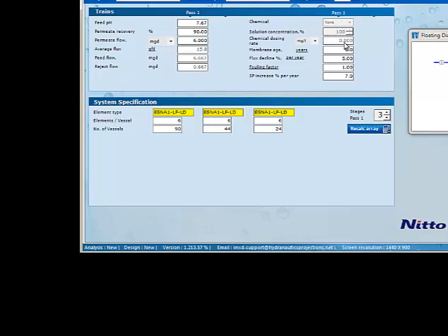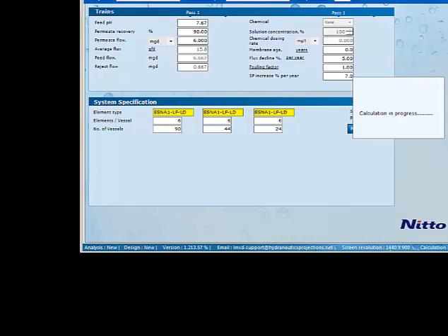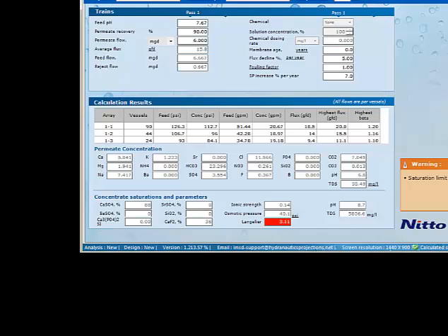And then we've got different chemical additions that we can choose. Look at different aging. It's going to tell you how much chemicals you want to put into this. So for now, let's just leave this as none. This one doesn't actually use any chemical feed that's there. So now the next step is to hit run, and you'll see this flow diagram came up, but let's run it again just to make sure everything is okay.